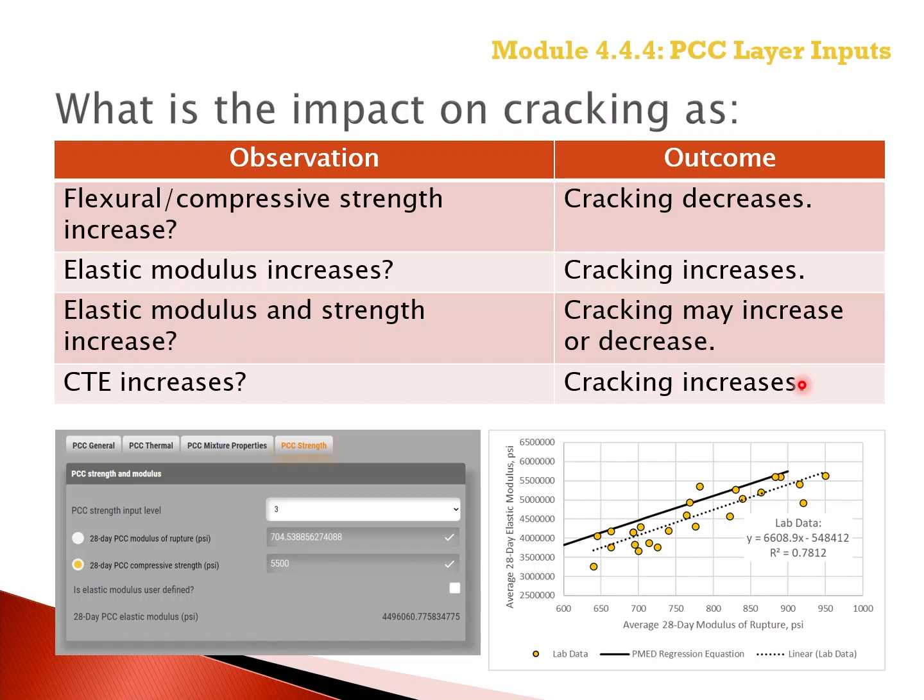So greater stresses at the top and bottom of the slab, and so potentially greater amounts of cracking, assuming a constant strength and constant elastic modulus.